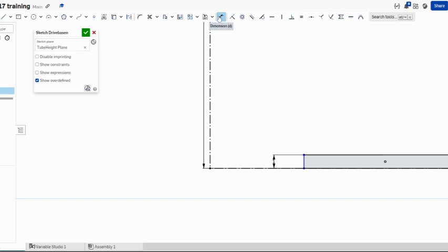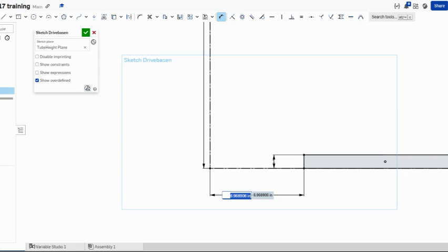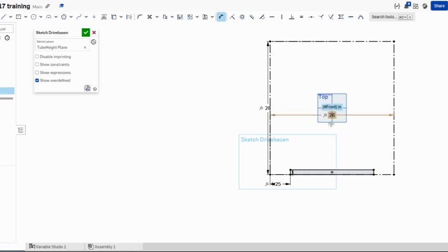And I'm not setting that distance. I'm now going to go in and hit the letter D to dimension. Click there, and then so 1 dot, so distance from edge, there we go. And because this was a center point rectangle, and the center is vertically constrained with the origin, it automatically resizes the way I want it. So that's fantastic. And I'm just going to do the same thing over here and make sure you see how it's touching there.